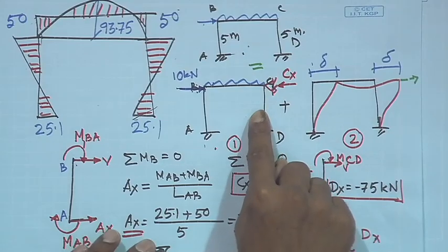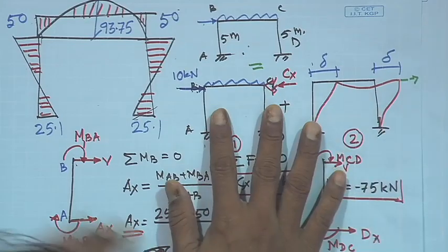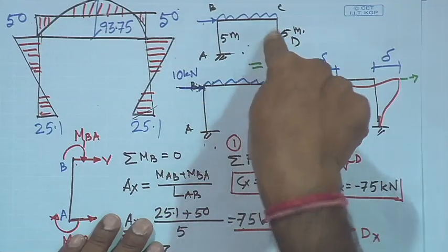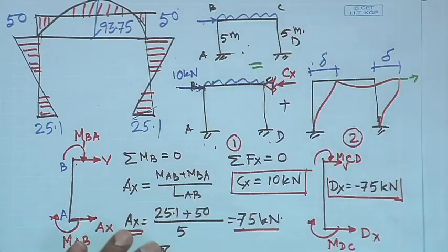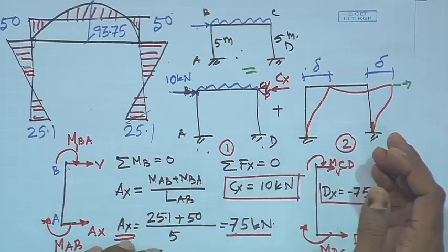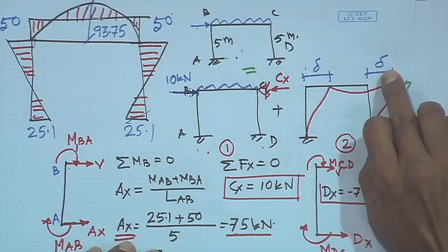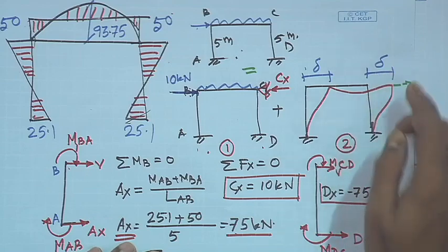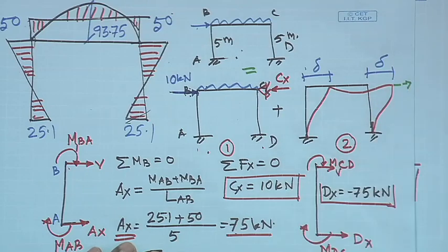Now, we are almost at the final stage. Now, what do we have here? What we have obtained in this is our first sub problem, this is the second sub problem, but if we add them, that should give this value. Okay. Now, it is again very simple. Instead of 100 by EI, you could have given unit displacement, unit sway here, and get what is the F value.